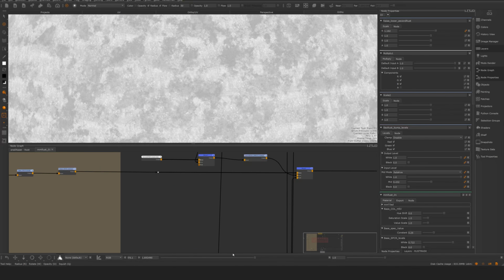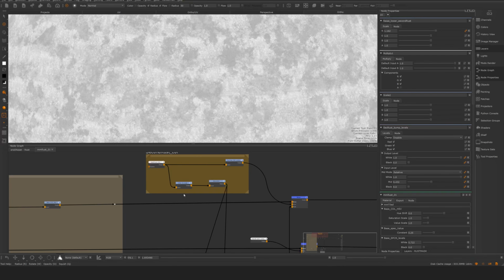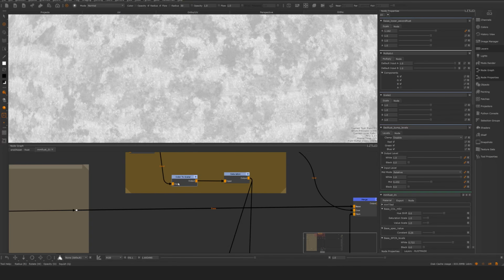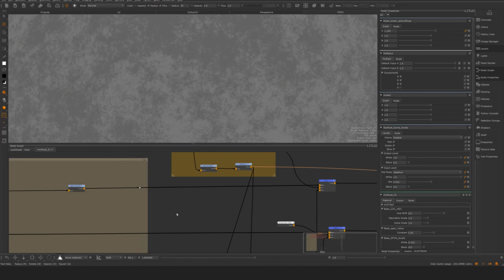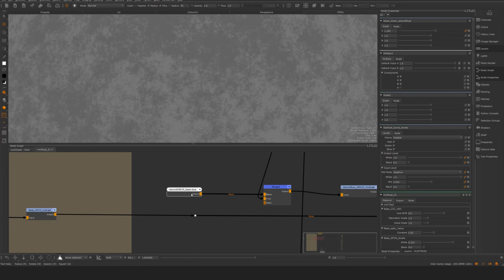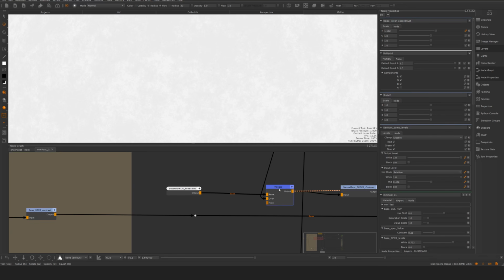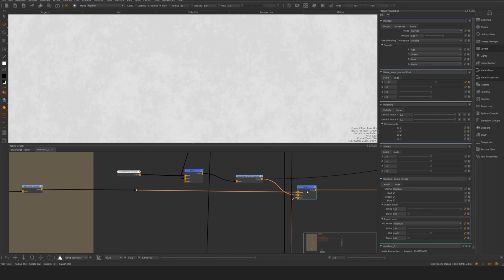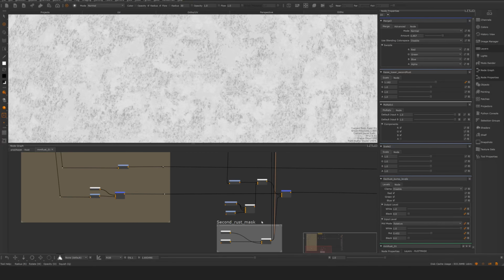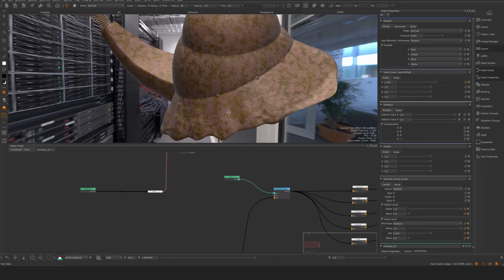We have the incoming color value that is run through a color to scalar operation, and I'm desaturating it. So here I'm taking whatever colors we have, using a color to scalar operation to put this into scalar values, and then I'm just desaturating this so it becomes grayscale, and then I'm using this in various operations here. For example, I have the specular roughness, and this is the base value of the specular roughness. I'm using parts of this on top to give the specular roughness some additional breakup here. I'm having a contrast operation for the specular breakup, and then I'm applying it here using the mask. We also have here the bump. Looking here at the outside again, and this is what we get.